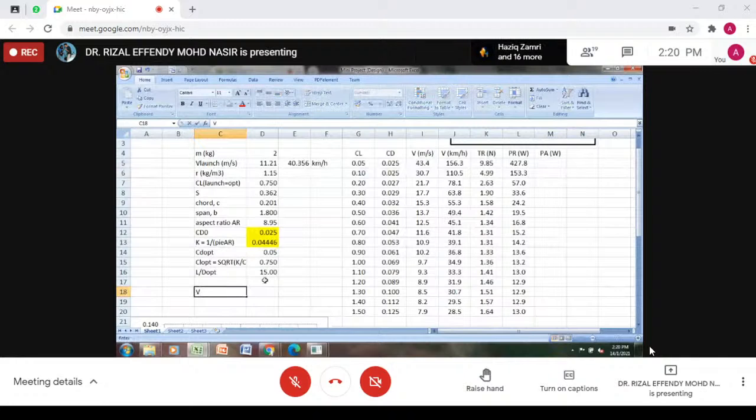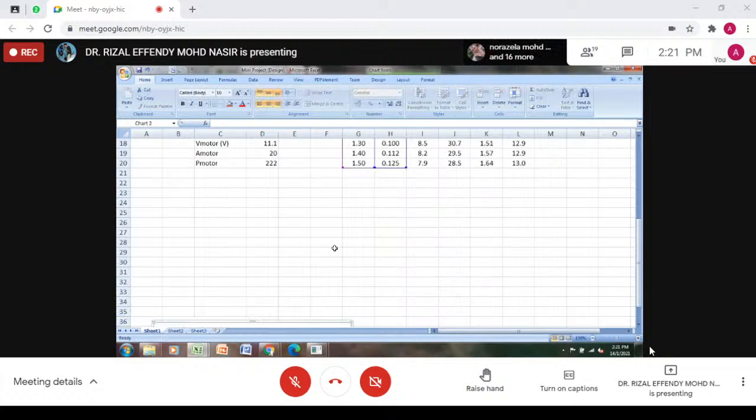motor voltage. Okay, motor. Okay, let's say kita pakai 3 cell punya sistem, maknanya 11.1 volt. Okay, mana saya tahu 11.1 sebab satu cell adalah 3.7 volt. Okay, so voltage of motor 11.1 and you are using 25 A or 30 A ESC. Selalunya kalau 30 A ESC, motor you maximum rating probably around 20 A. Okay, so motor ampere adalah 20 A. Okay, jadi motor power, maximum motor power adalah voltage kali dengan ampere. Simple je, itu je. So it's 222 watt.